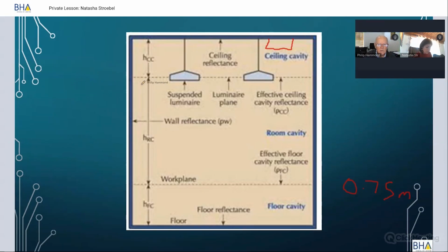So I said, here's the dotted line, which goes through the reflector. That's the reflector of your high bay. But how do we know what that height is? Well, it depends on if you say that your room is 7 meters and the chain that it's suspended to, depending on the kind of roof that you're dealing with. And usually you suspend it so that all the lights are at the same level, because you need to calculate to see that you've got the right amount of light on the working plane. Then you will know what that height is.